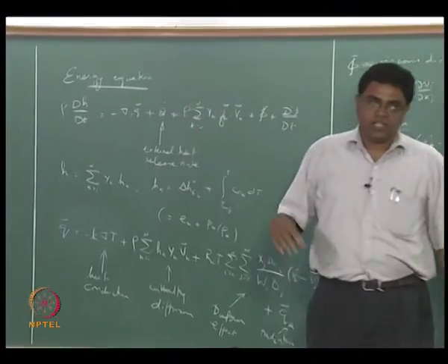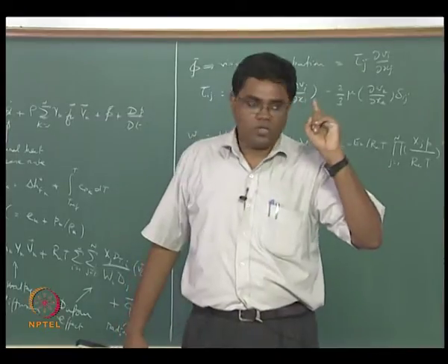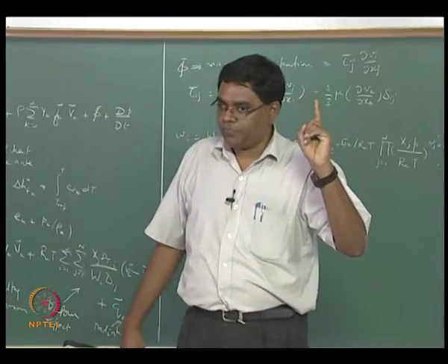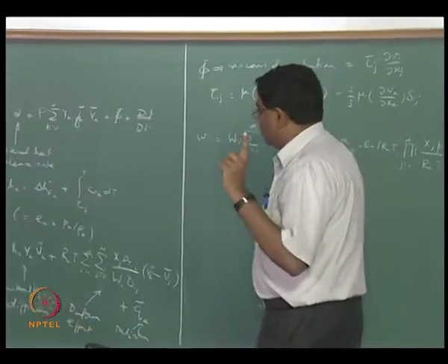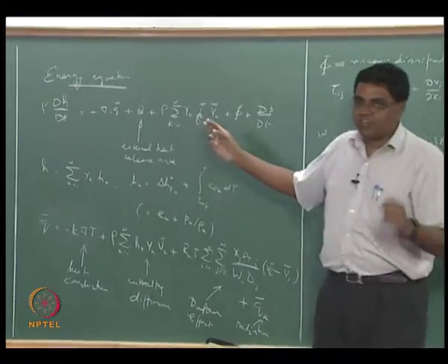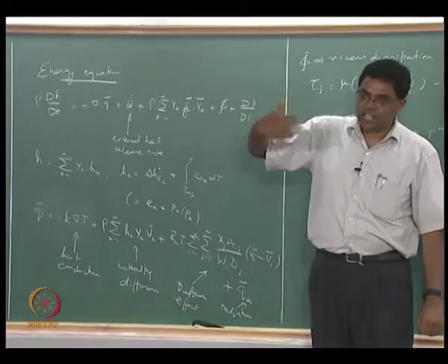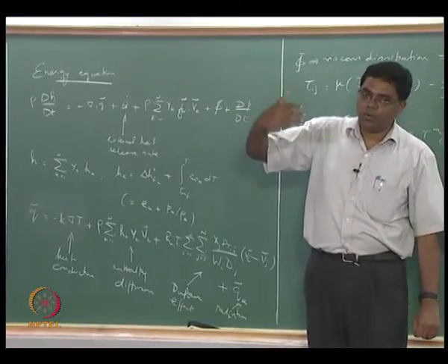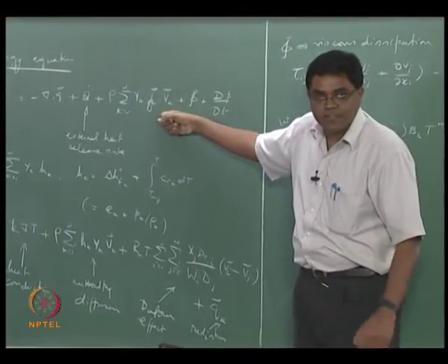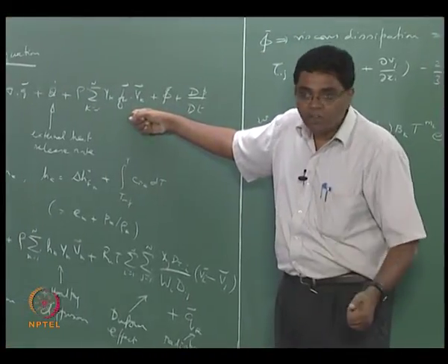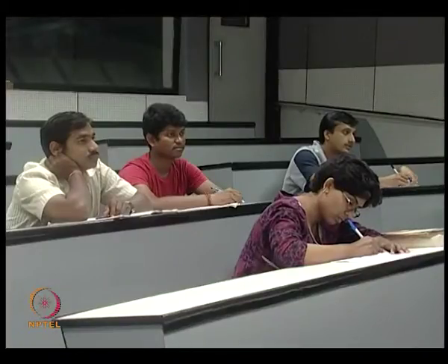While you did that, in that equation you had a body force per unit mass term showing up, alright, and the body force got dotted with the mixture averaged velocity, alright, but each species is actually getting acted upon by a body force that could be unique to that particular species in the first place, and secondly the work done by the body force is on the species velocity.